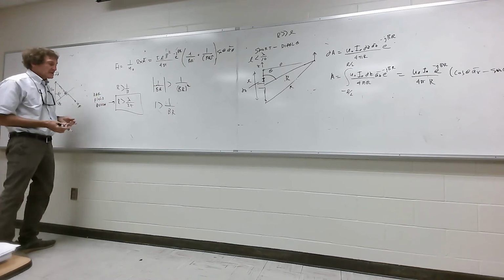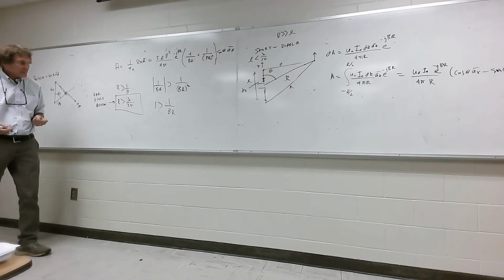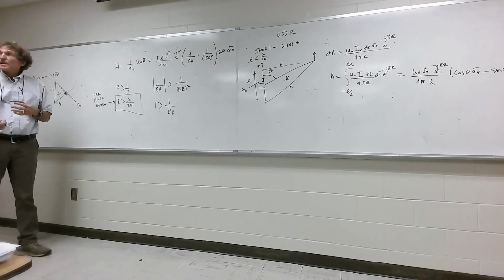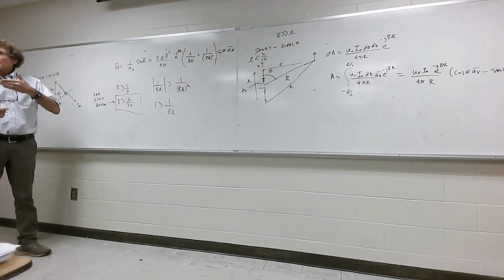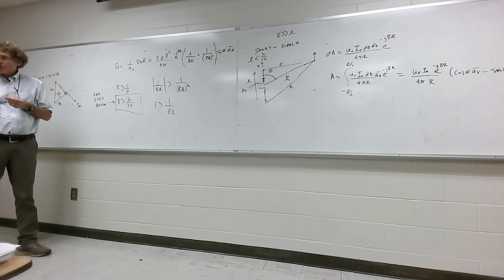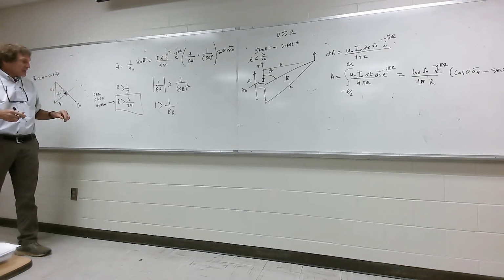So when I'm at any distance r greater than lambda over 2 pi away from an antenna, I can assume most of the electric field strength, and therefore the electromagnetic power density and energy, is propagated. It's not coming back. Y'all follow me? And this is an arbitrary thing, but it's an important point of distinction.